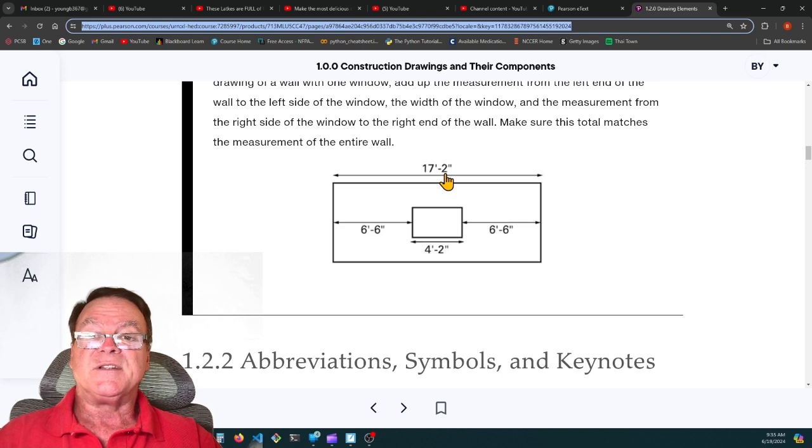If there's a discrepancy between the blueprints and the specifications, if the blueprints show you have 12 spare 4-inch PVC conduits coming out of the electrical room, capped off and not used, and then the specifications say 12 3-inch PVC spares, we need clarification.